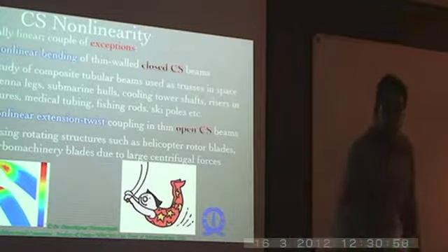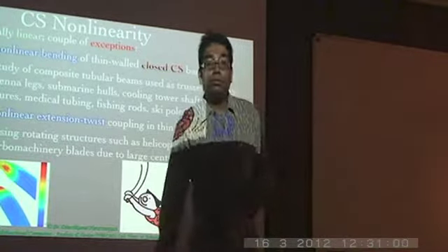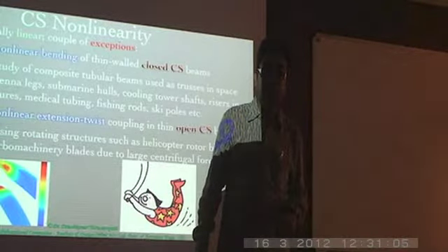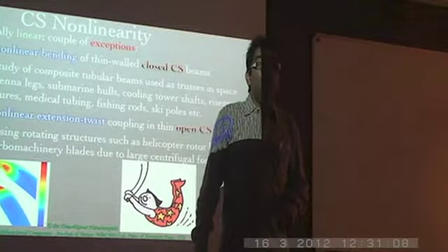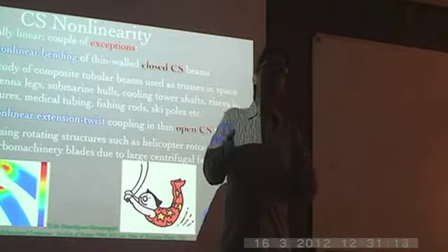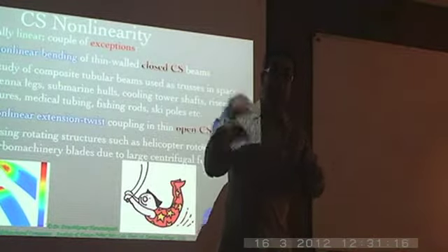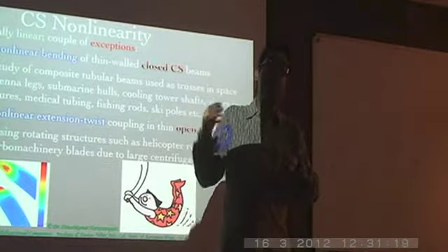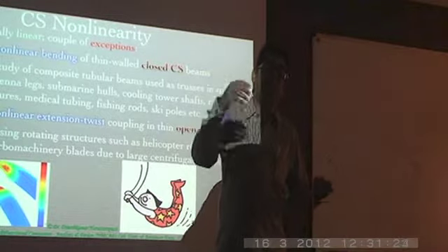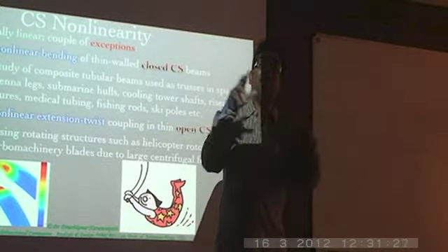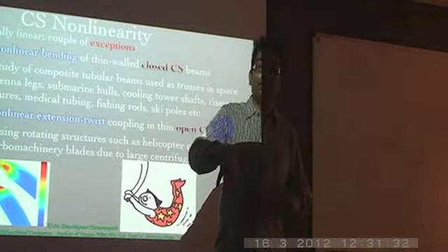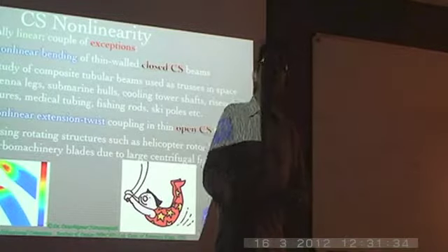Well, is it also because we have the centroidal axis and the shear center which is off in the open sections, so the torsion and also the bending effect come into the picture because of extension? That is a separate effect. Okay, so it is not that which is causing the cross-sectional nonlinearity to occur. The cross-sectional nonlinearity, the source is always the in-plane warping. Okay, so it's the in-plane warping which changes the shape of the cross-section and or the size of the cross-section, because of which you change all the stiffnesses, and that's the source of that.